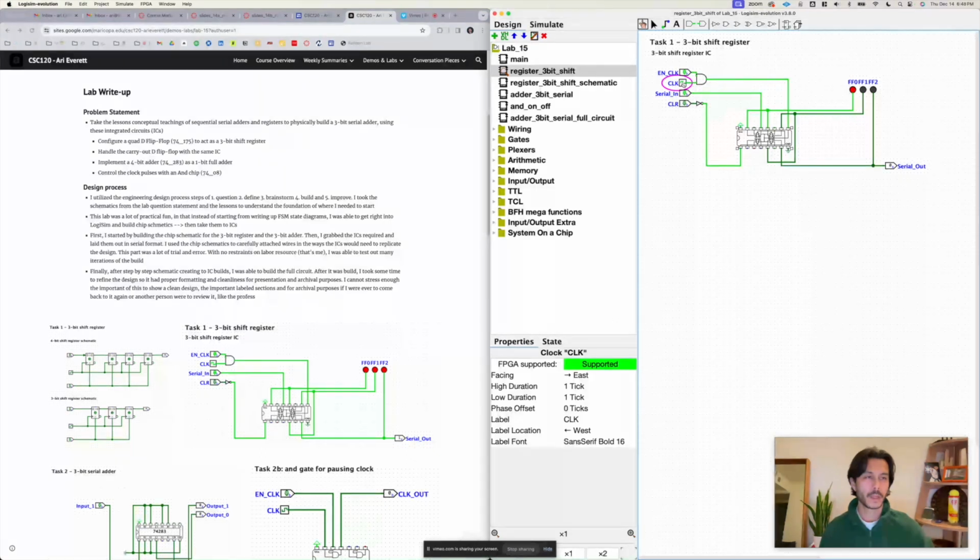Let's enter in 111. And remember, it goes from least significant bit to most significant bit by inputting it first on the left. Now I hit the clear and it clears out. And serial out here.